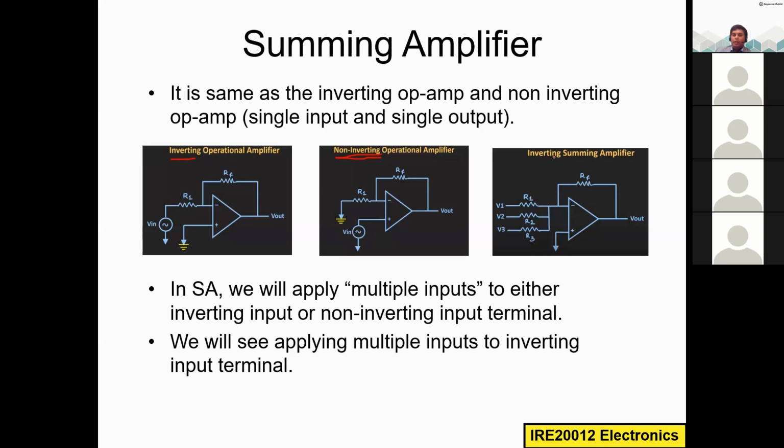So here in summing amplifier, it can be an inverting summing or non-inverting summing amplifier. So it depends on where you are applying the input. In this case, this is called an inverting summing amplifier. So here we are applying input to this negative input terminal.